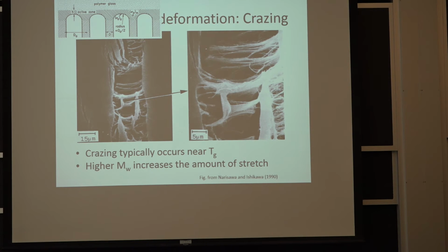But the little clip with the hole that you just put to hold the bag of bread. No? Yes? Good. So that plastic clip, if you just fold it, it's going to lose its color, right? It's turning white. So that's called stress whitening. And at the small scale, what it means is you have craze formation.